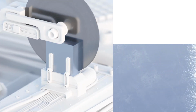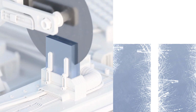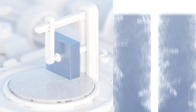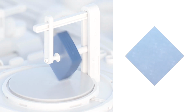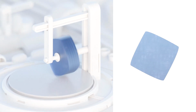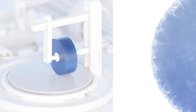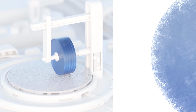To produce classical optics from glass, they are first cut using abrasive tools. Mechanical cutting and grinding are destructive procedures which cause the formation of cracks below the surface, the so-called layer of subsurface damage. Cut pieces are blocked together in a shaping mechanism and mechanically rounded. New cracks of subsurface damage appear at the edges of glass pieces due to the brittleness of optical materials. The nature of the subsurface damage depends on the type of glass processing.